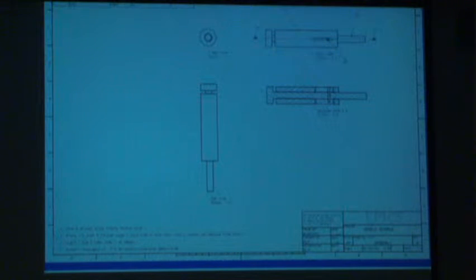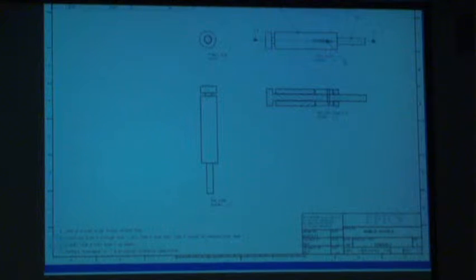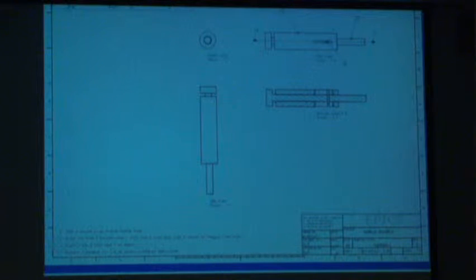So the notes on the last print told you the material, the surface treatments that you do to the material. Okay, so those are very important to specify. Because I think I indicated a Rockwell 40 minimum heat treatment and a glass bead blast. So those specify how hard the part is and what the outside surface is like. So if you didn't do that, that sliding fit between that inside and outside part could be something else, right? If you just leave it as machined or if you did some other surface treatment. So it's important to fully specify not just the geometry, but anything else, processing steps that you want done to